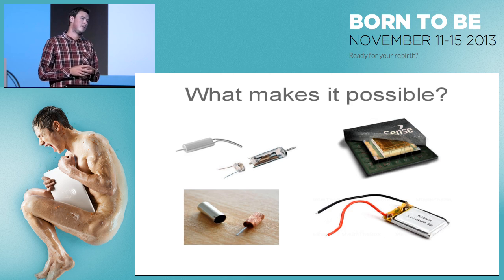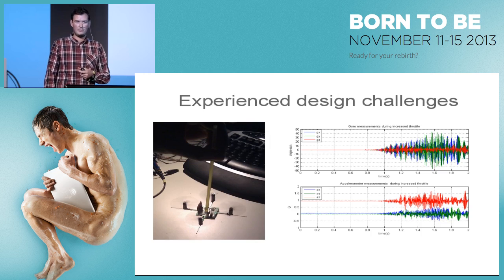The Crazyflie consumes about 5 watts of power when it hovers, but the battery can produce almost 20 watts. So you can put on bigger motors or something if you would like.